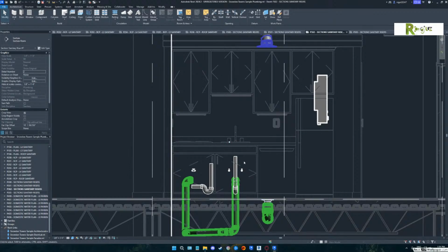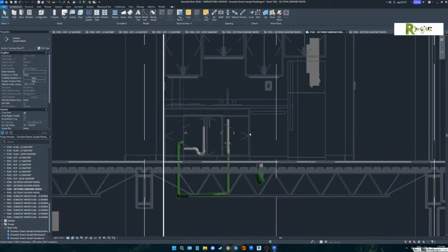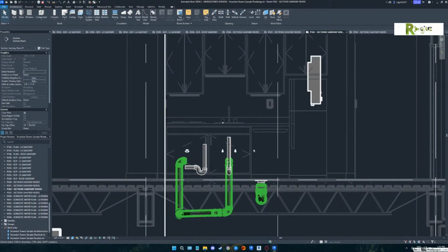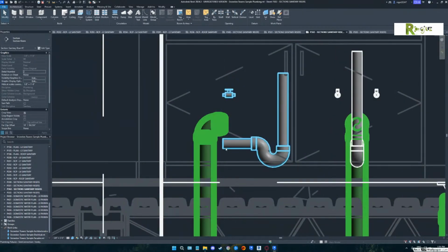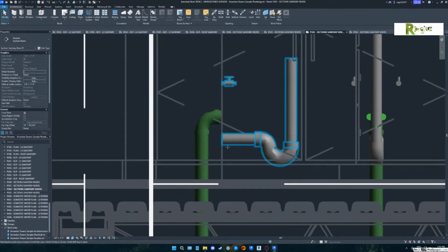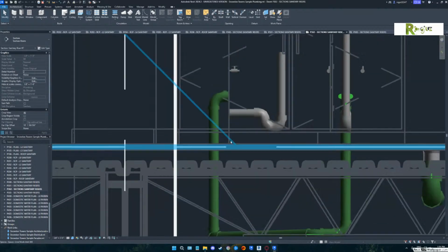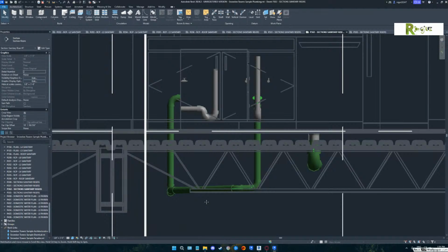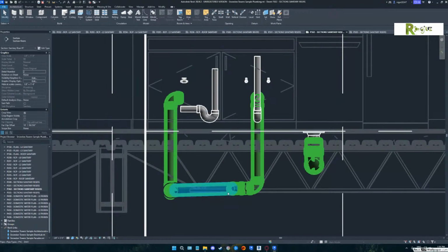I personally don't look too highly at the plumbing. I would expect your drawings to be much better. Your drawings had better be much better than that. On top of that, boy, look at the nightmare where they've run that pipe underneath the floor. Zoom out just a hair. Right in line with the bottom web of that joist, it's probably clipping through that joist. As a matter of fact, you can see it's going through the joist.